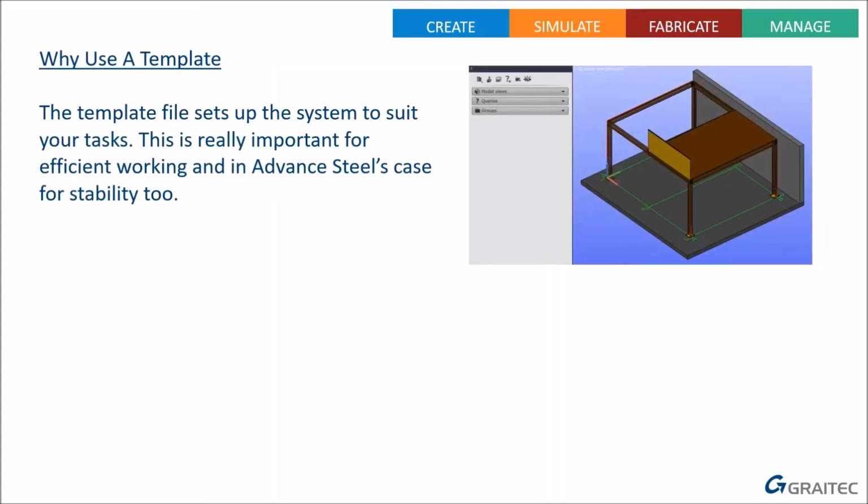What is the template all about? Why should you use AS template? Well, the template sets up the system to suit the tasks at hand. And it's really important if you're going to be working efficiently in Advanced Steel, because with Advanced Steel, we have known people use other templates or other files as the basis for their models, and it's produced crashes and strange behavior left, right, and center. So although it's not necessarily obvious what the setting is, it's really important you use an approved Advanced Steel template at all times.